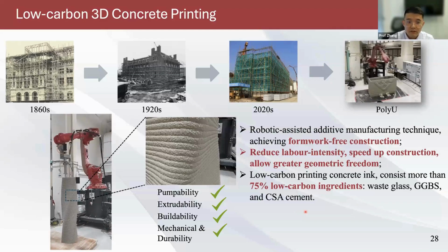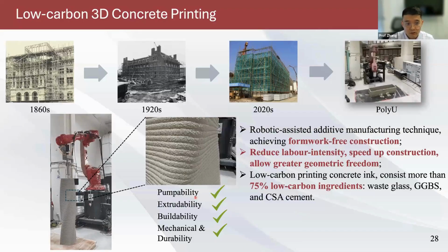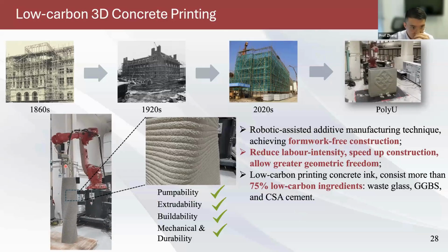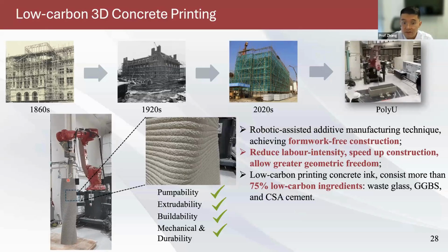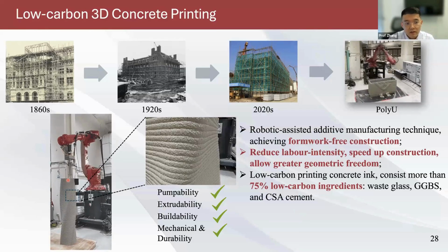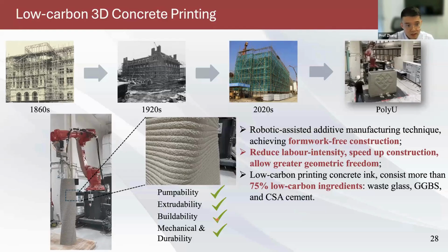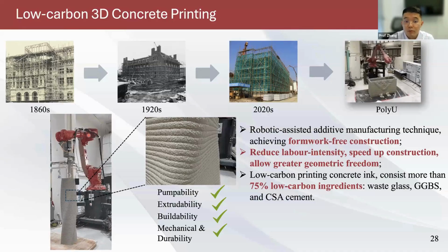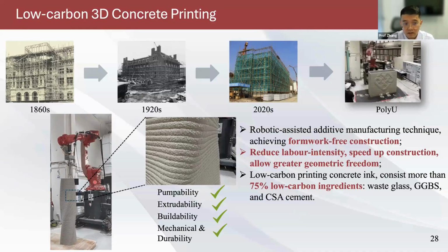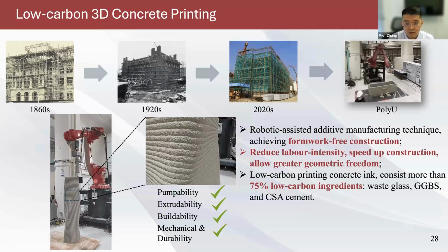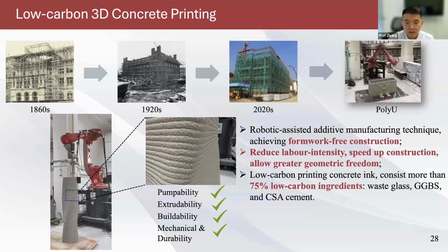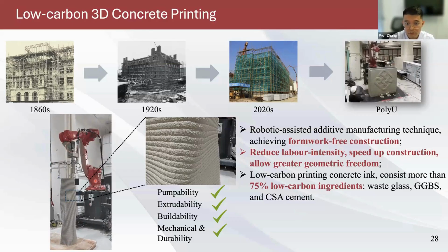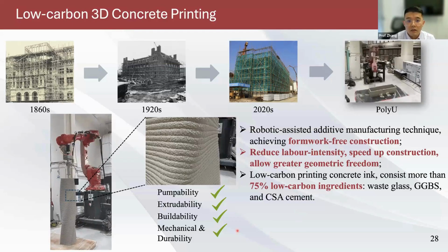So it can achieve very good pumpability, which means the concrete can be pumped to the nozzle very smoothly. Extrudability: the concrete can be extruded out without any defects. Buildability: the concrete can be printed up to this column, which we added up to 2.5 meters, so it has good buildability. It can be printed very high without significant deformation. And we tested the mechanical and durability performance of this mix, and it is very good.